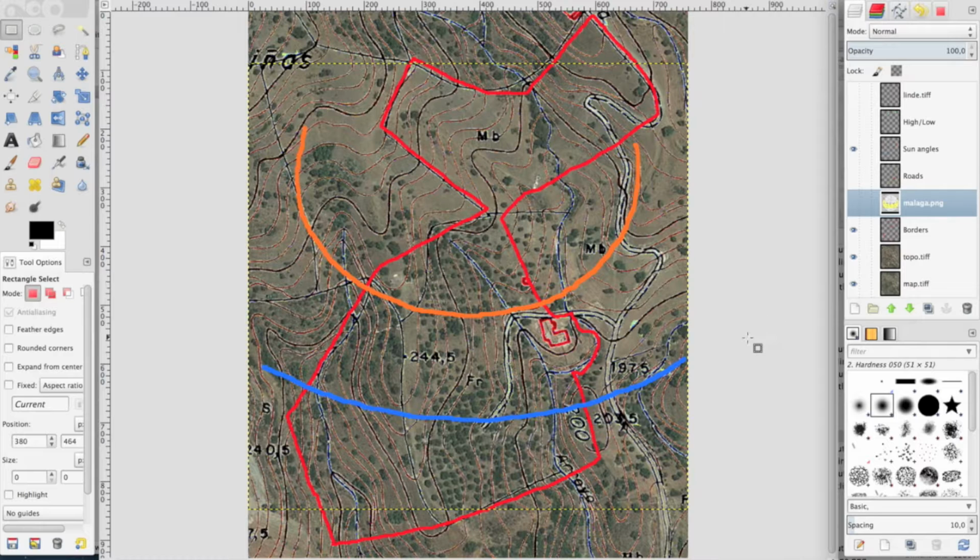Now, on this site analysis, we have to remember that we had a hill going up here on the right-hand side, and we have a hill here on the left side of the house. So actually, once you get below a certain point, which is probably here, and probably here for the summer line, then you can't see the sun in the house anymore. So if you want to do a thorough site analysis, you add these angles in and say, well, this is the point in where the sun goes below the ridge and no longer casts any light on the house. If you're doing a site analysis like I'm doing here, those things should become obvious when you do the aspect of the house, but it is a nice thing to remember when you're doing this.